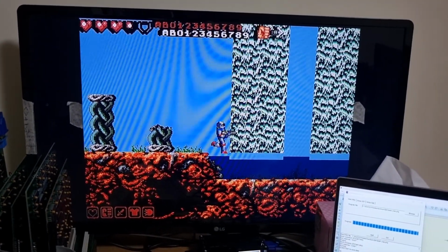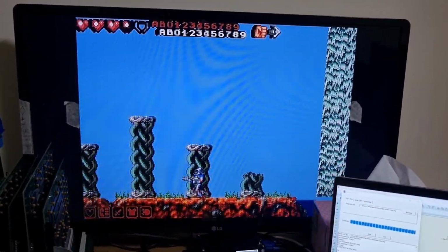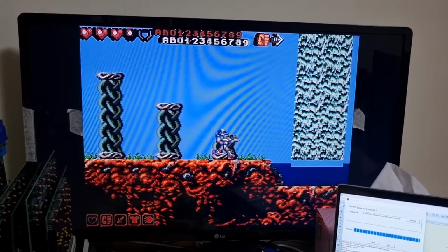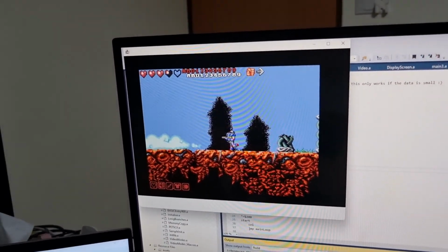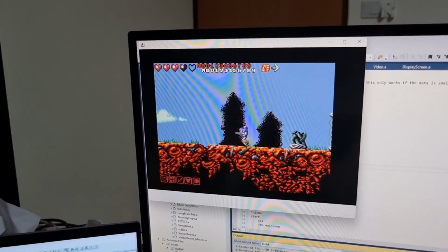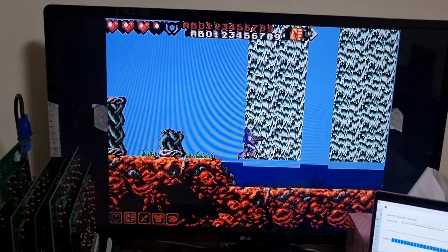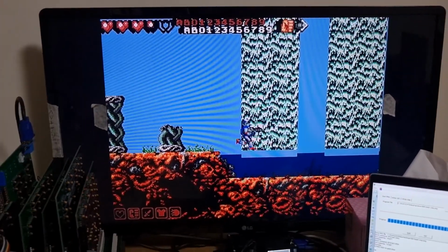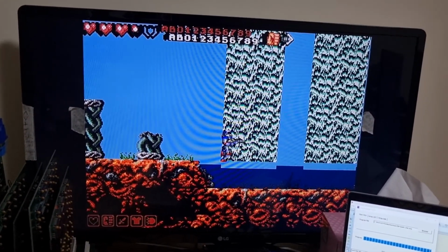The only thing that I can spot at the moment is that the second character's layer is being drawn twice, and that's because, oh yes, that's right, on the emulation I've got the last layer initialized as the mode 7 layer, but obviously the last layer on this one is the second character's board, and the second character's board is displaying the data from the previous demonstration, which was demo 7 just now.